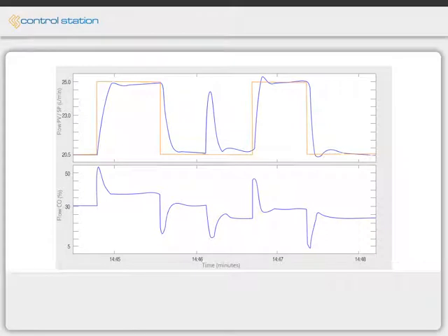The controller output to process variable behavior described by an ideal FOPDT model is constant, but real processes change every day because of plant upsets and changing plant conditions, phase changes, or process conditions and behaviors for a specific unit of operation. As a result, controller performance can degrade with time and periodic retuning may be required.